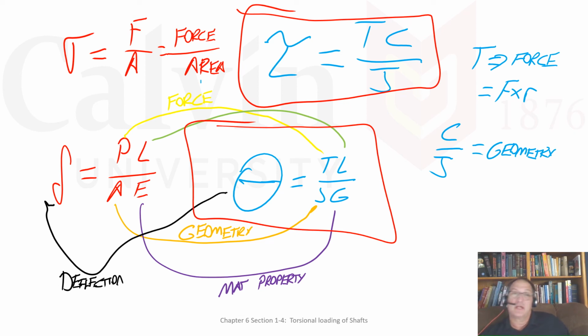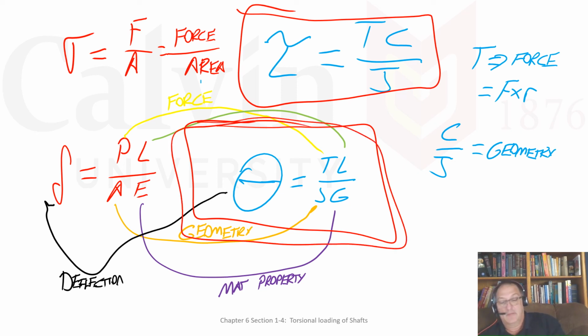We're going to do the same things. We're going to hit a situation. We put a torque on a bar, and how much does it twist? And that's a displacement question. So we go to our displacement equation. We're going to say if we put that torque on the bar and it deflects this much, what's my stress? Can I tolerate the stress? Yeah, that's a great question. So now we'll have an allowable shear stress.